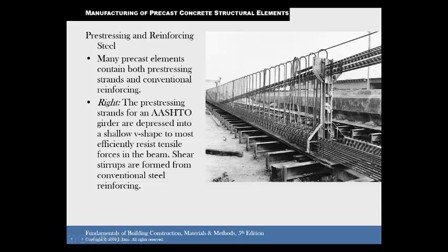And remember, steel is strong in tension, and when you have a structural beam or girder, it's going to bend in the middle. So you got all the steel on the bottom to keep it from breaking. Concrete is strong in compression, so up here on the top, where the beam will dip, that's more compression, so there's not as much steel there because the concrete will take care of that. And then you got even more steel coming down following the stress of the bending. Does that make sense to everybody? Any questions on that?